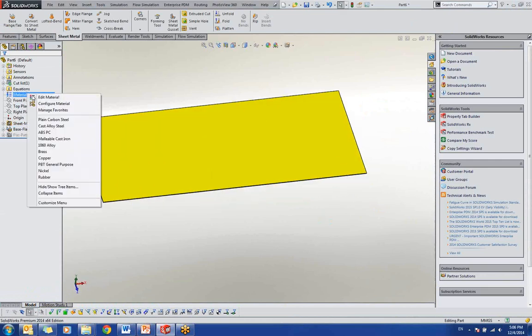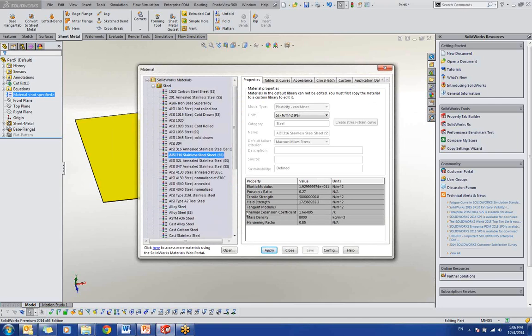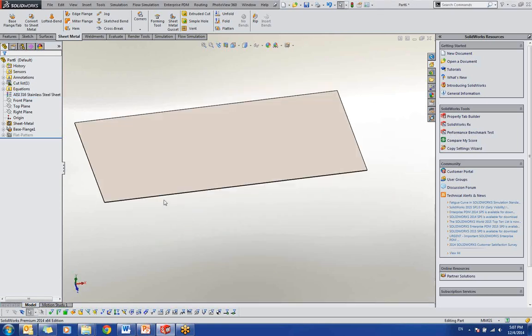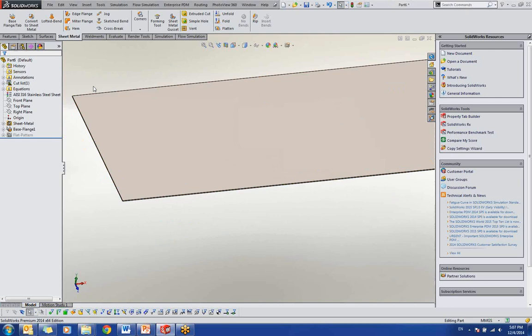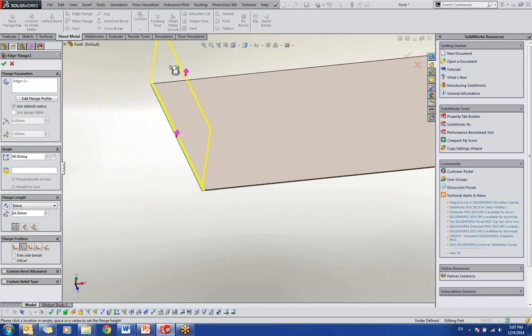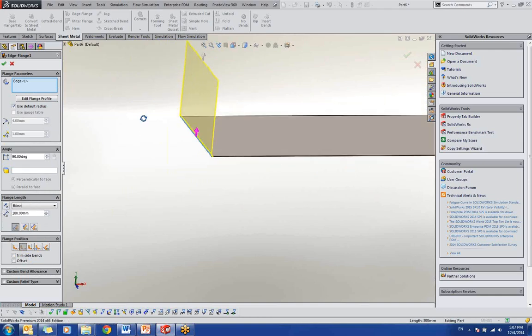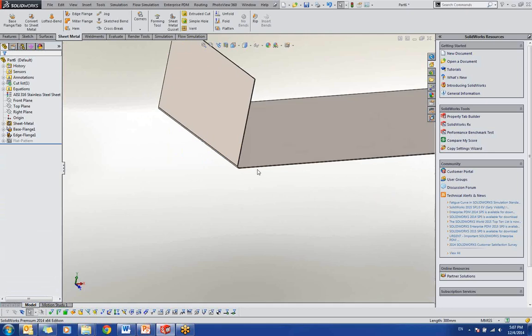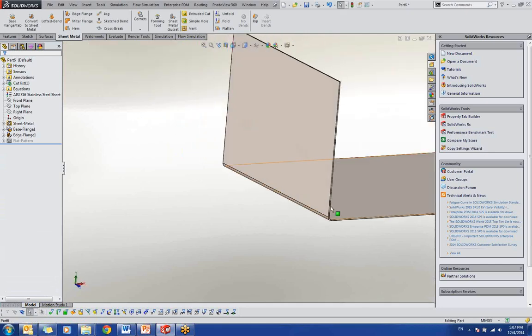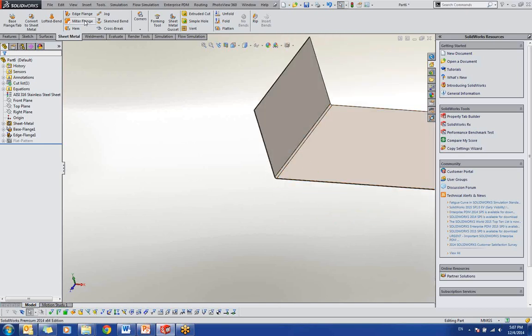Okay, now I just make the material first. Same, I use the alloy steel. Now I use the stainless steel sheet flat first. Now I want to make another sheet metal here, assume a bend here. So I have an edge flange. I click here, and then you see that a flange will come out. Another sheet metal will come out. I bring it around 200 mm, and then like this. Done. You'll see here, another sheet metal has come up. I already bent it.